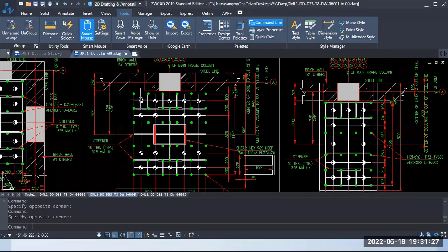As per Appendix D, there are certain procedures to check the concrete capacity, what we call the CCD method, the concrete cone method, in which we calculate the concrete breakout strength and what we can say pullout strength. Based on that, we provide this additional reinforcement requirement here.